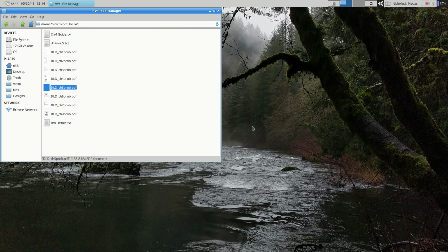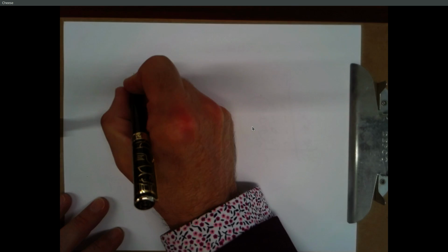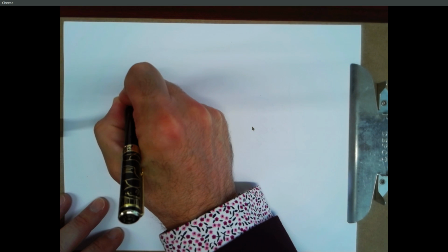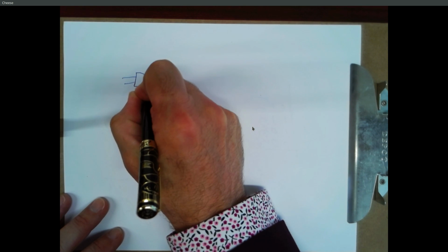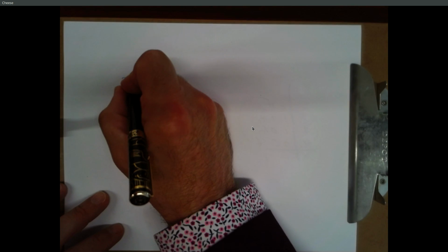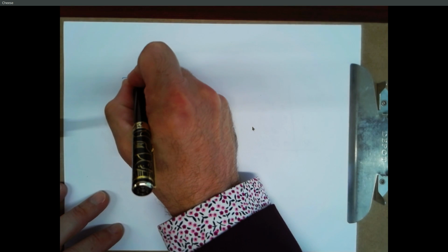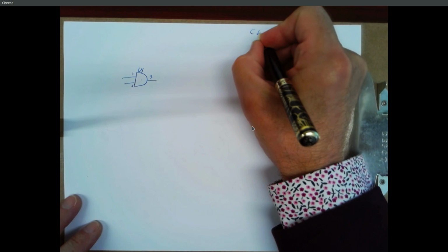So one comment on drawing circuit diagrams. I noticed this in some of the schematics from Lab 5 and from Lab 6. Suppose you are building your traffic light circuit. You know that if you have an AND gate, you draw a picture of the AND gate with the regular AND gate symbol. You label the pin numbers and you put a package designation, like U1 for example, and up here in your component ID block,